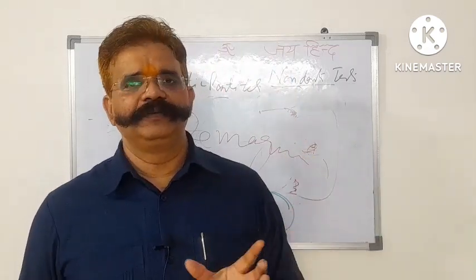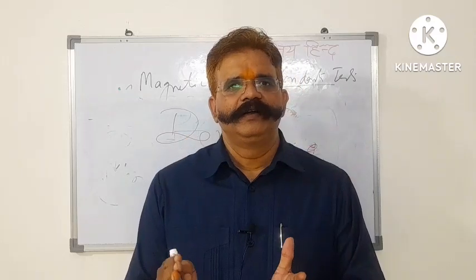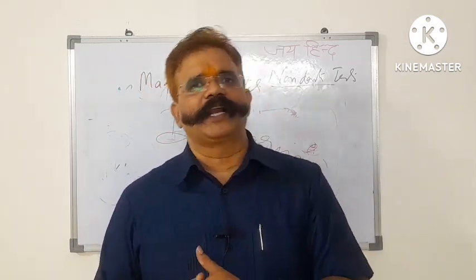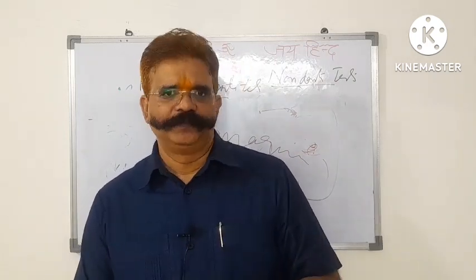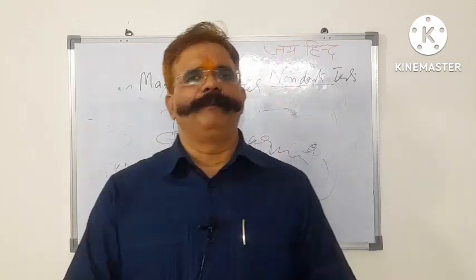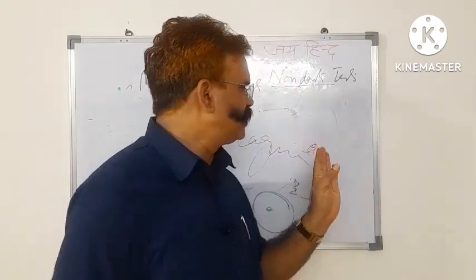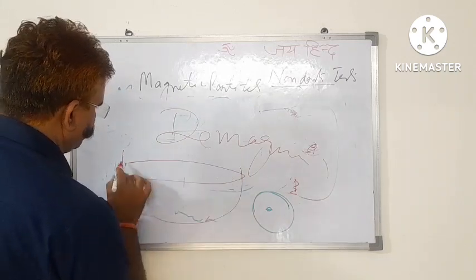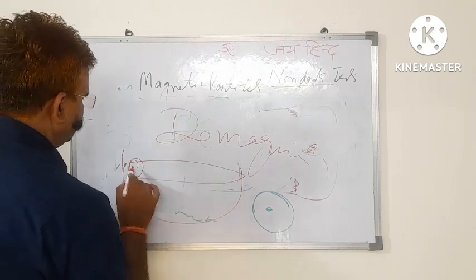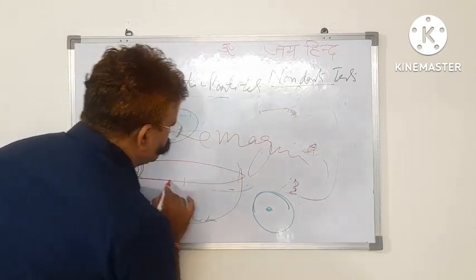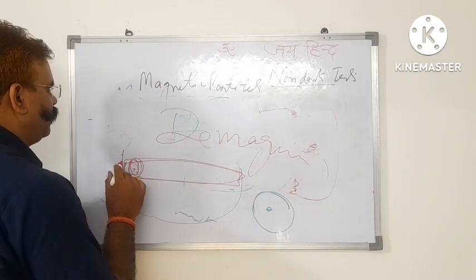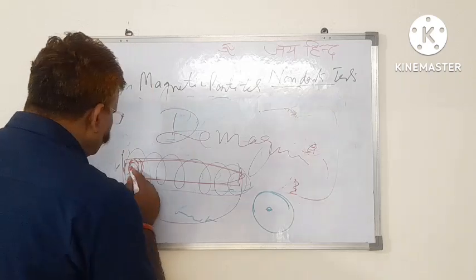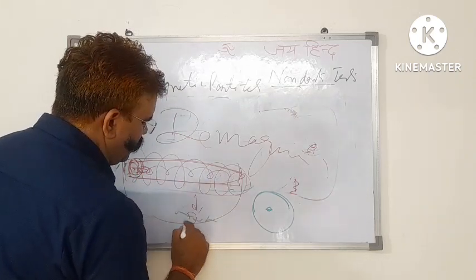Suppose this component is a part of an aircraft and you have left it like this, the component is magnetized, you have placed it in the aircraft, there are certain gyro equipments in the aircraft, they will show error with this magnetic field. Like this, many other complications are there. So after the test, these items have to be demagnetized. For this, there is a demagnetization bench. In that, the component is kept and moved from one place to another place over a rail, and there is a varying alternating current field. Due to this alternating current, this magnetized component will be demagnetized.